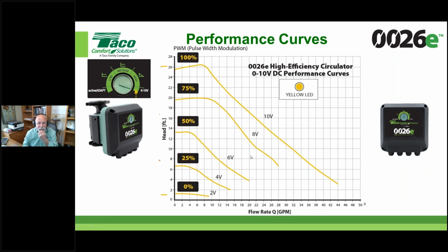So let somebody control us either with pulse width modulation, which is somewhat of a chopped signal where we look at a time length and if the unit's been powered up for a fraction of that time window, then it looks at that based on the whole time window and proportions itself back in what speed the circulator is running at, or the good old 0 to 10.